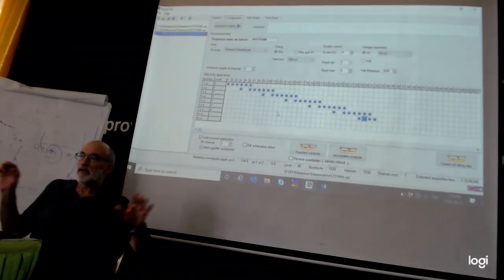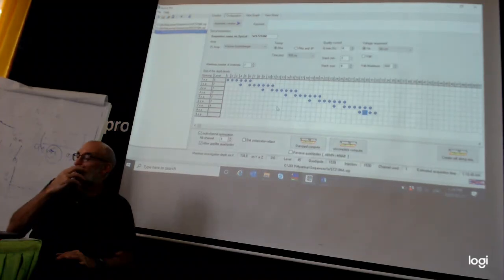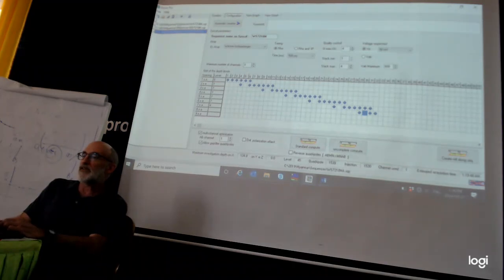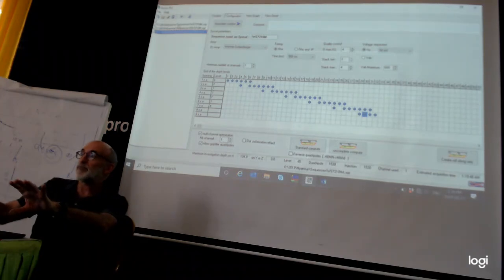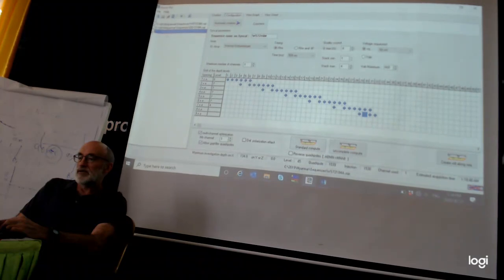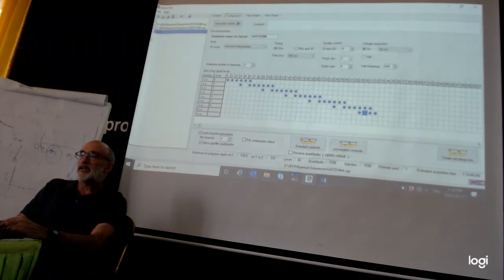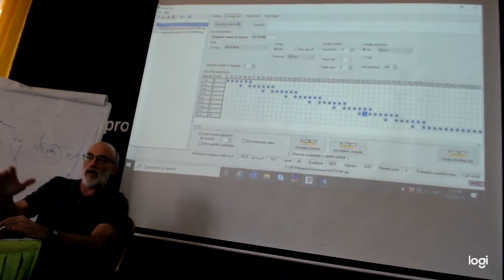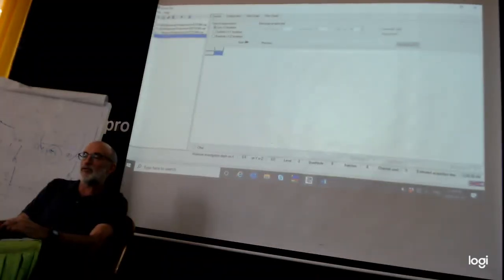The line running north to south was measured at 10 meters, but it shows 8 meters. That's because we kept changing the file on here and it changed it, and that's what we uploaded. Since it was changed after measuring and then uploaded, it says 8 meters instead of 10. So anytime you want to change a sequence file, take one and save it as a new one, or just choose new and make a whole new one from the creation stage up.